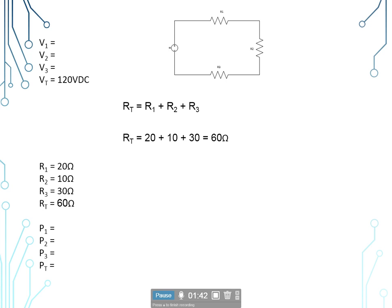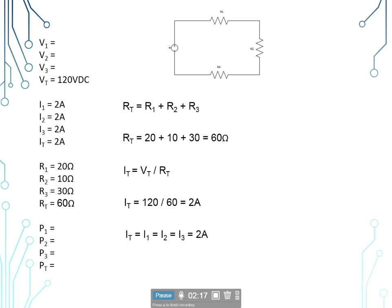Now that we have our total resistance and our total voltage, we can find our current for this circuit. I sub t is equal to V sub t divided by R sub t. So we have our total voltage of 120 volts divided by the total resistance of 60 ohms to give us 2 amps. Now in a series circuit, the current remains constant through all components. So I sub t is equal to I sub 1 is equal to I sub 2 is equal to I sub 3, in this case equal to 2 amps. So we can populate those other 3 currents for the individual components.